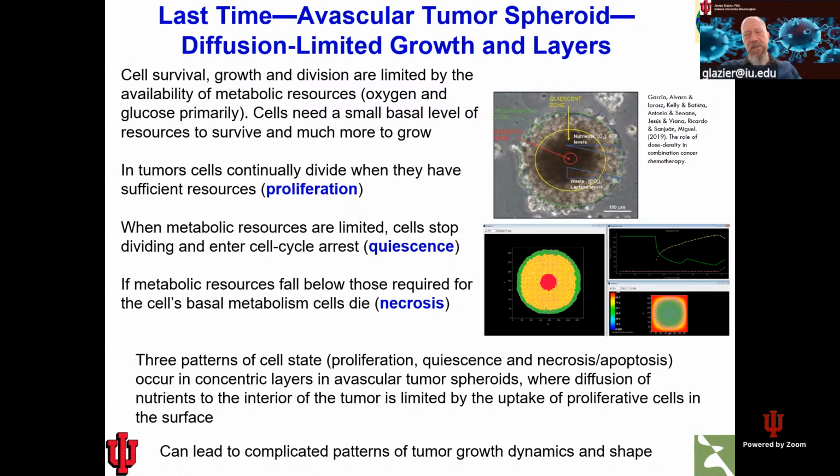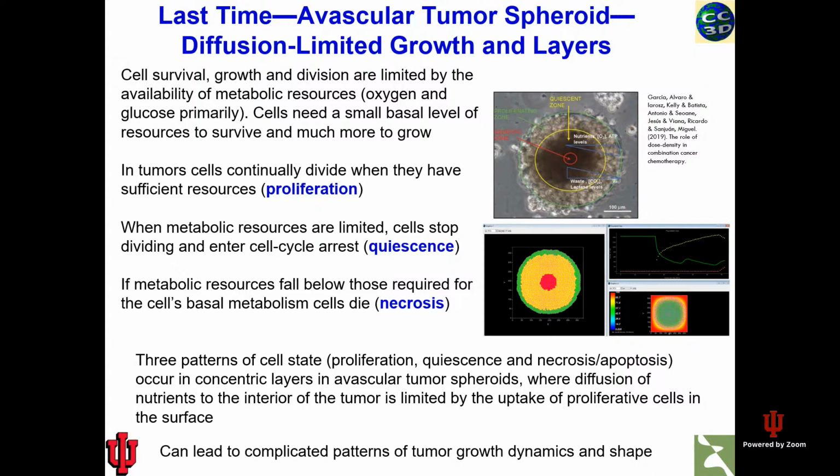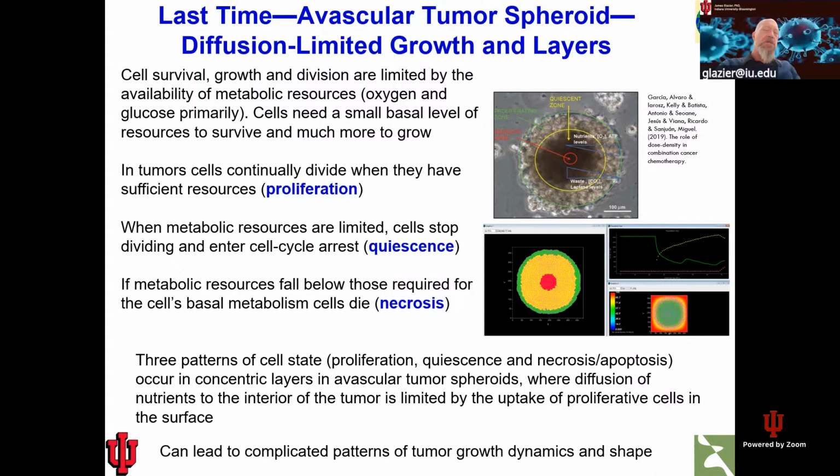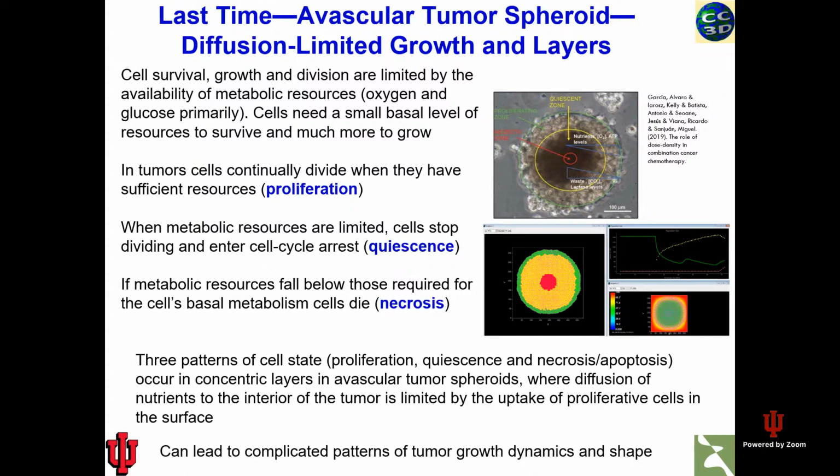Did that ever get fixed in CompuCell, or is that still a bug in CompuCell, Pedro? Which bug? If you use frozen cells and you change the type of the cell to change the diffusion constant, for example, it doesn't update.